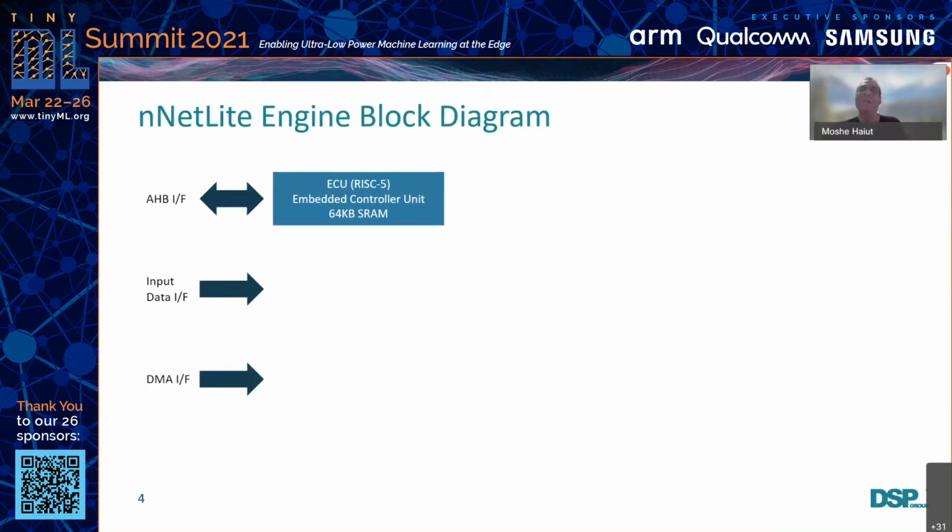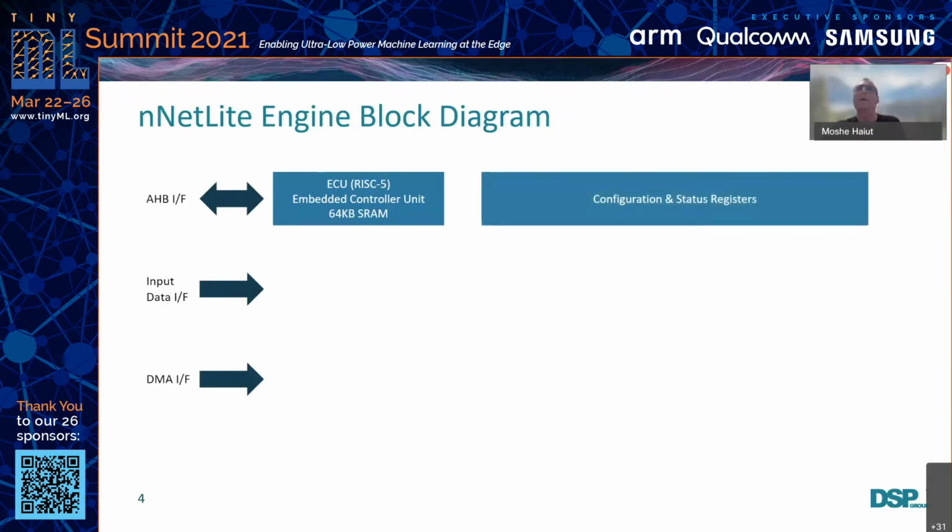Between the layers themselves, it wakes up, configures the setup for the next layer, and then goes to sleep again. And finally, at the end of the inference, it communicates with the host controller. There is a bunch of configuration registers that actually contain the descriptor of a full layer, and this runs independently of any other external assistance for a whole layer.